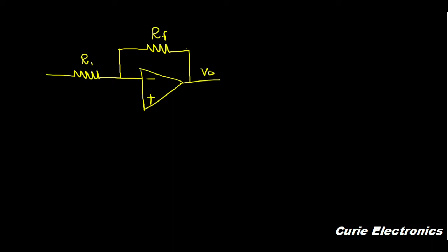And what about our non-inverting terminal? This has to be connected to ground. So here we'll apply the Vin. This is our input voltage. Now we have to find what is Vout. How do we find this? Using KCL, we'll find what is Vout.